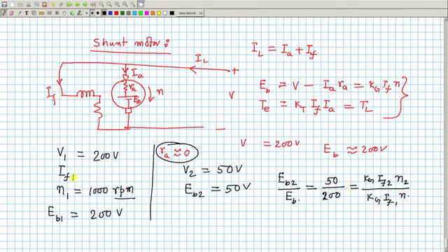Now, if this current was IF1, what is the field current here, IF2? See, this is the beauty of the shunt field connection. How much will be the field current? You have reduced the voltage by 4 times. So, your IF2 has to become equal to IF1 by 4, because field resistance I have not varied. So, IF2 by IF1 will become 1 by 4, no doubt.